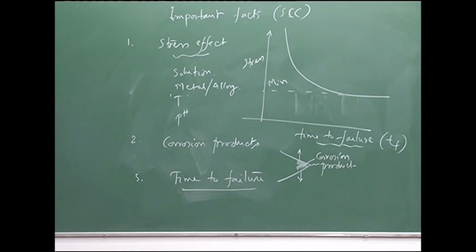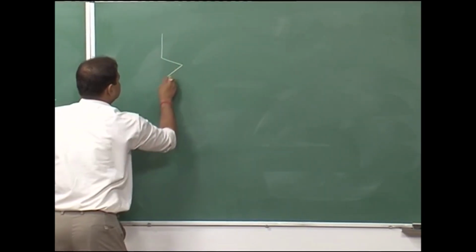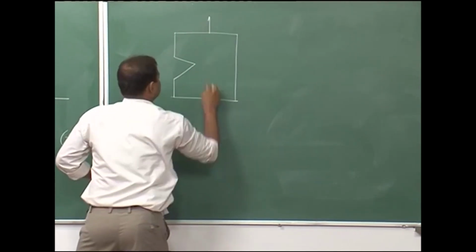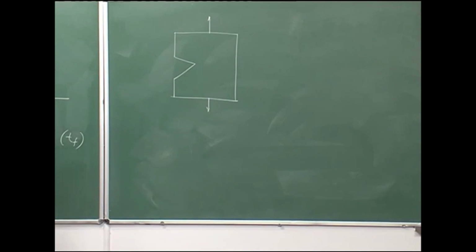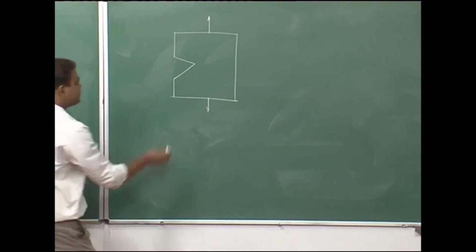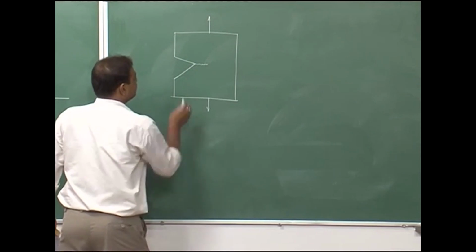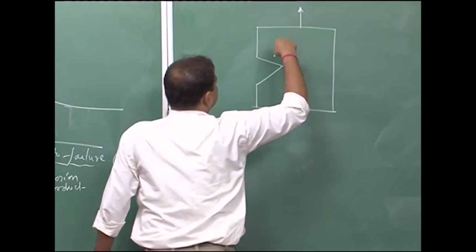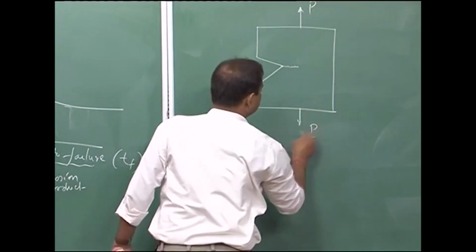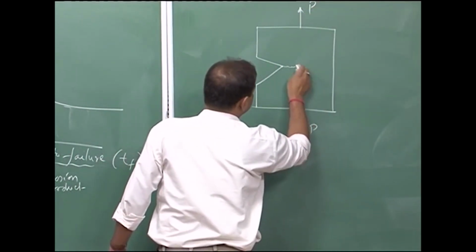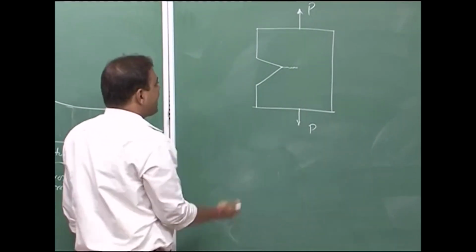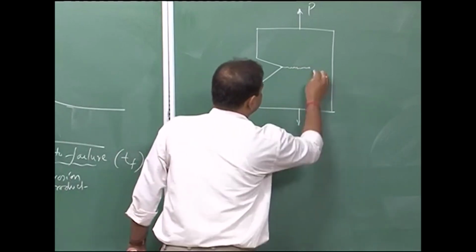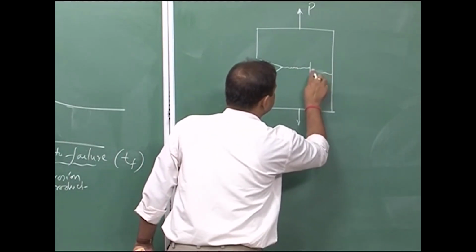now if you see this, let us say this is my crack tip and this is my total object. Now, we have this one under tension. Now, gradually the crack surface is growing inside the material, and if this is a constant load, gradually the remaining section has an increase in stress, and as it grows like this, finally you have a small ligament.